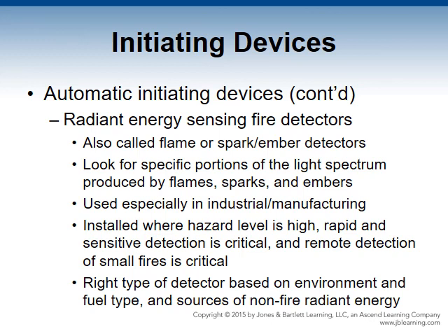They are used in many environments, but especially in industrial and manufacturing environments where exposure to non-fire related sources of radiant energy is greater. They are usually installed where the hazard level is high, rapid and sensitive detection is critical, and remote detection of small fires is crucial, in such places as petroleum processing, storage, and loading facilities.